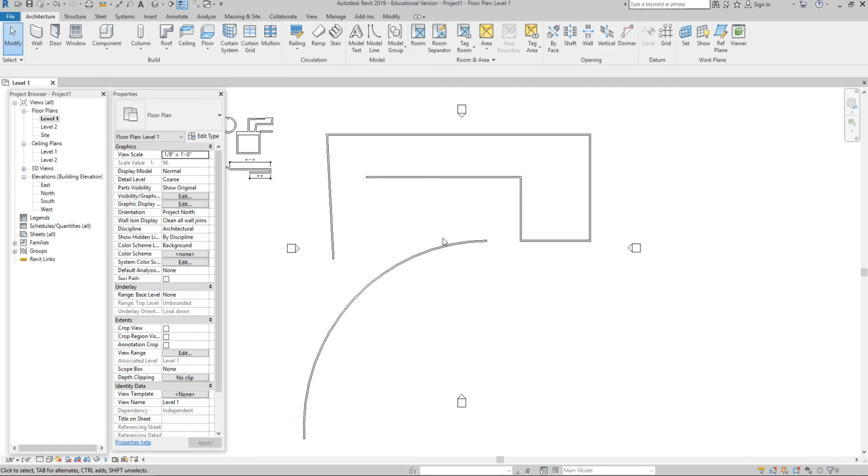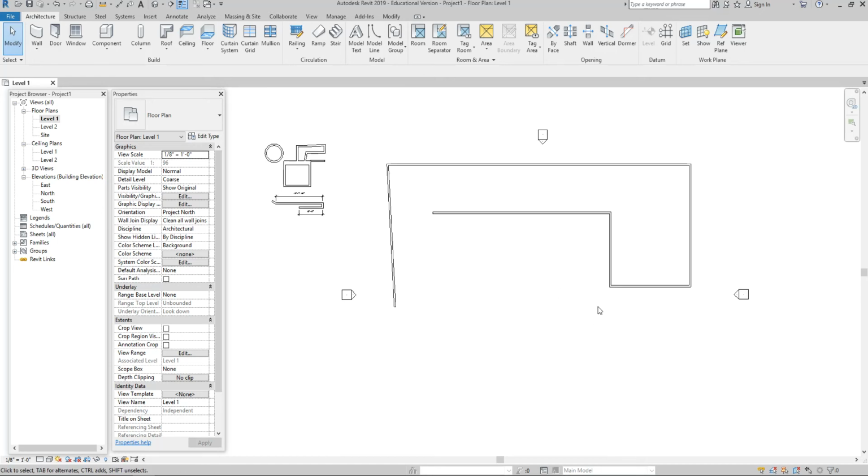And we'll talk about our last topic today before my computer restarts, and that is going to be reference planes. Okay. Revit has a built-in function called reference planes. And reference planes, if you want to give them another name that would maybe be a little bit more descriptive, you can call them construction lines, right?